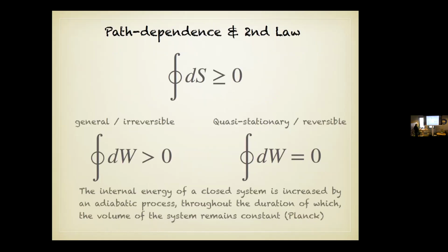And the second law, in the classical formulation, would simply say, okay, in the Carnot formulation, if I go through a circular process in my thermodynamic machine, a Carnot cycle in this case, or a simple compression decompression cycle, then in a closed system the entropy has to be non-decreasing.